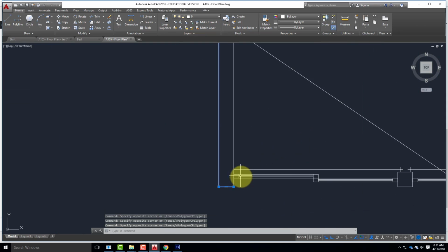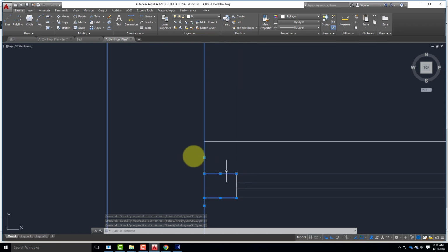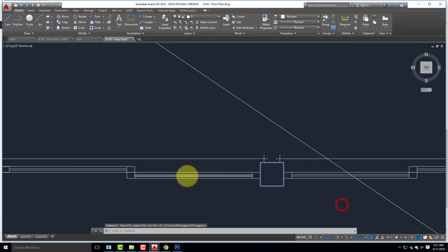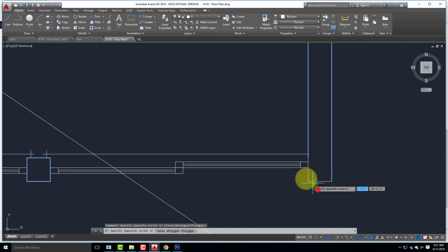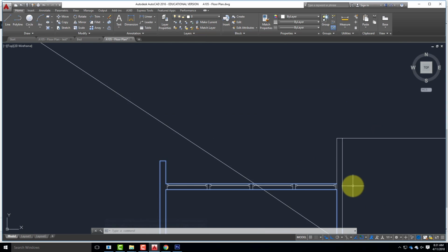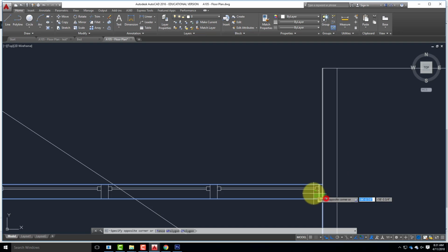If you accidentally selected something, like if I accidentally selected that line, hold down the Shift key and drag over it again, or click over it again, and it'll deselect that particular piece. For those of you that are in 136, that's different. In Rhino, it's Control to deselect. In AutoCAD, it's Shift to deselect.